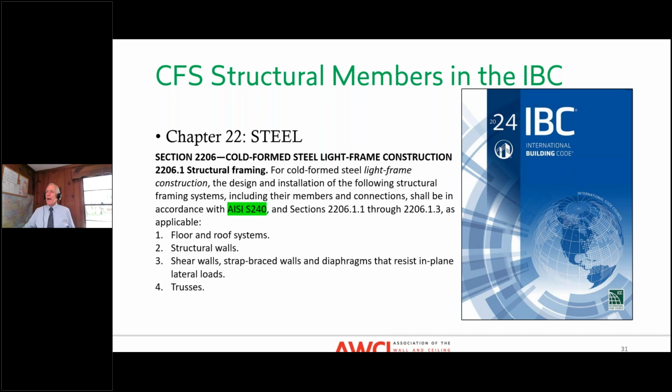references AISI S240. And it specifically calls out AISI S240 as being applicable to floor and roof systems, structural walls, shear walls, strap brace walls, diaphragms that resist in-plane lateral loads, and trusses. So again, a little laundry list might be good for you to know what these things are: the floor and roof systems, wall systems, lateral systems, and trusses.